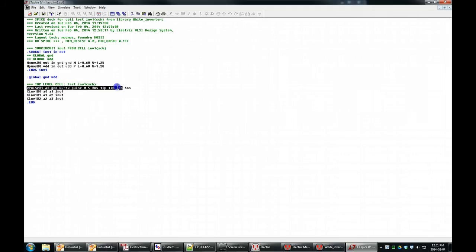So here's our pulse. This is the line for that. DC, it goes from node A0 to ground. And at pulse 0 to 5, we can look up the syntax for that. Three inverters, three X's, X, INV, 0, 1, and 2. That's just the names of them. Three instances of INV1, and you can see that they are connected in cascade, or series, but series really is not the appropriate term for that.